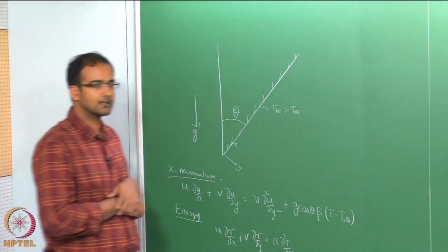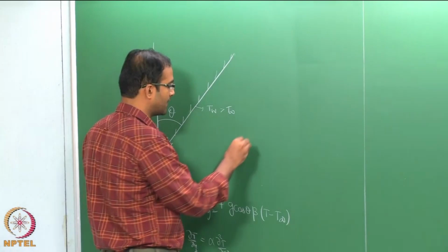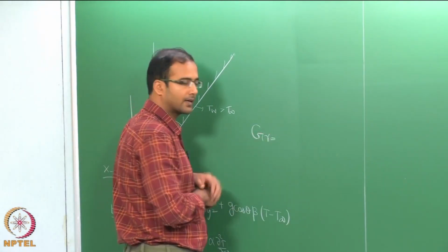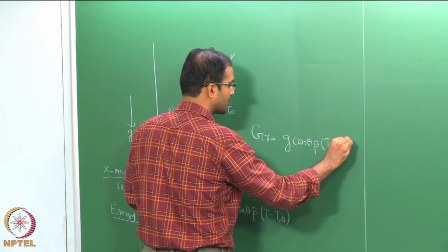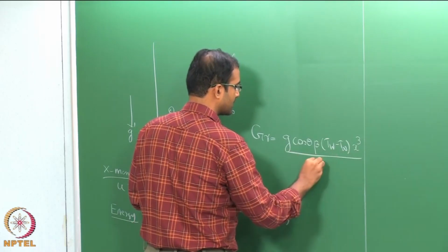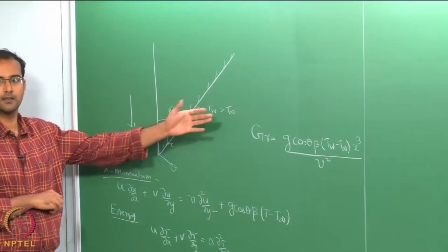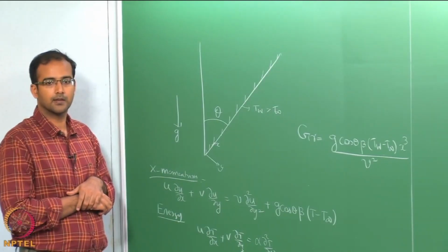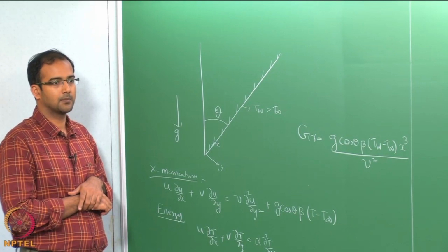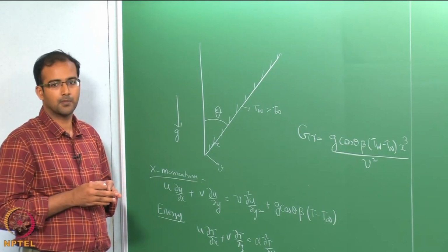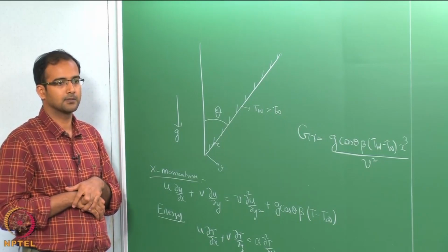Okay. So, therefore, in such a case we can have the same solution whatever we did for the vertical flat plate, and we will only redefine the definition of Grashof number. Okay. So, we will just include g cos theta into beta T wall minus T infinity into x cube by nu square. So, we will just include the inclination angle cos theta directly into the definition of Grashof number, so that whatever solution that you already encountered, whether it is the similarity solution or the approximate solution, is still valid for this case with the slight modification in the Grashof number. Okay.